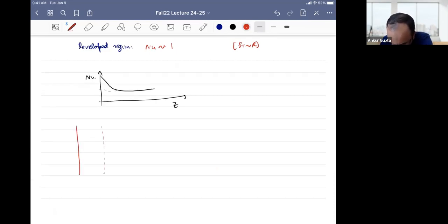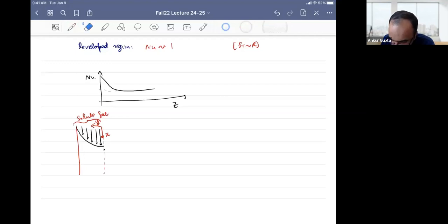about the falling film diffusion, right? Here I have some sort of falling film with some velocity. You calculate it first, right? And then some C naught was going in from here. Initially this was solute free, so nothing was being dissolved here. Just to clarify, we're talking about this falling film here, and then the solute enters through the film.